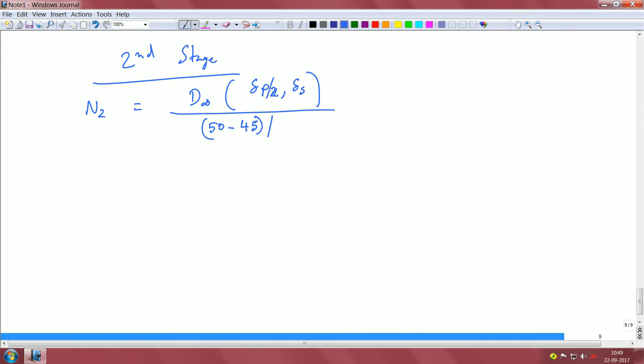We had 10 kilohertz, we downsampled it by a rate of 50, and we were at 200 hertz, and that is downsampled by 2, and we have 100. So, therefore, this is 200 here because this is the input for the second stage, and you do the math for this, which is approximately 111 taps. I mean this is the order of the filter, and you do the multiplications